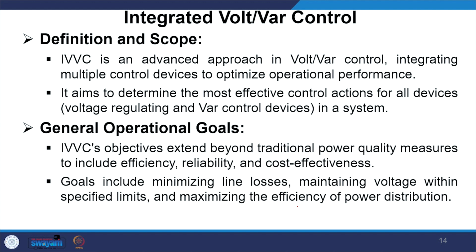The objectives of IVVC, that is integrated volt-var control, extend beyond traditional power quality measures to include efficiency, reliability and cost effectiveness. Goals include minimizing line losses, maintaining voltage within specified limits and maximizing the efficiency of power distribution.